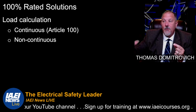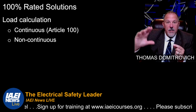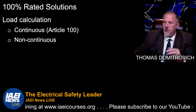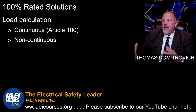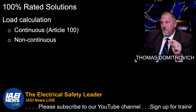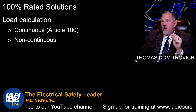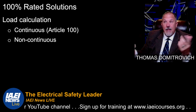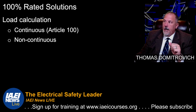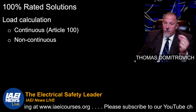If you look in the definition, it is continuous load, not continuous amps, it's continuous load. And it tells you it's the maximum current expected to continue for 3 hours or more. So when you think about loads, lighting, you think your lights are going to be on 3 hours or more. When you think about a hot water tank, will it be on for 3 hours or more?